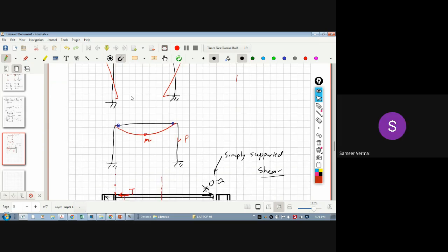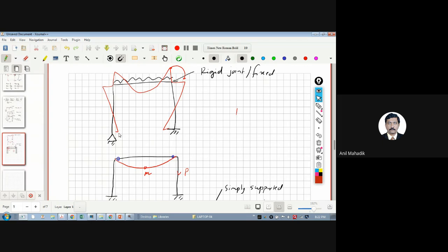Yes sir. Same cases at the bottom. Many times we may require supports as simply supported, meaning hinge supports. So in that case, what can I do? In Staad Pro, I will consider the hinge support like this. As it is a hinge support, you know that, let's say I am only considering this part as a hinge support.